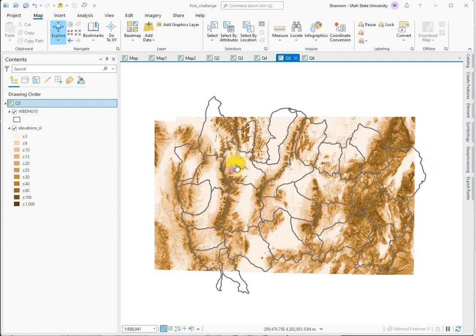Because we're working with a bunch of features here, we've got a raster data set and the polygons. This is another surefire use of zonal statistics as a table. So hopefully you guys are catching on that I am really trying to get you comfortable with going to zonal statistics as a default. It's really effective, and I'll show you some tricks in a second.